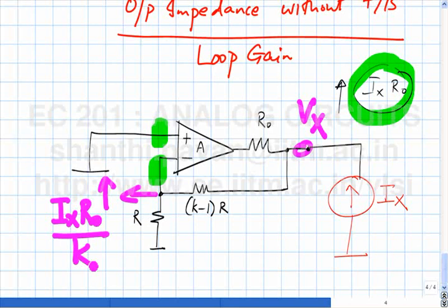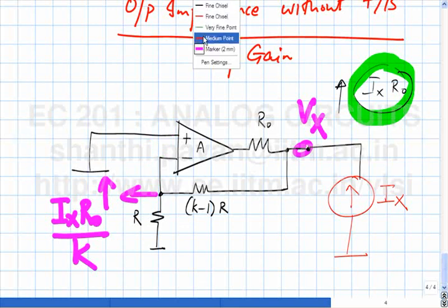So then what is the negative feedback loop doing? All that it cares is that these two potentials must be the same. If the two are not the same, it will kick the output in such a manner as to try and make these two voltages the same. So, what do you think happens the moment this voltage goes up in this fashion?